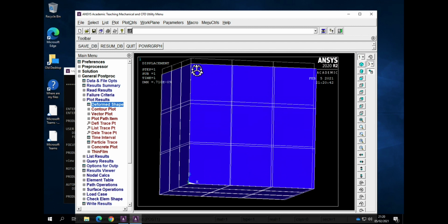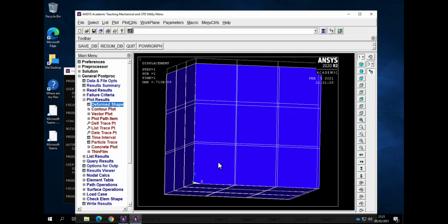I didn't think too much about the direction of the field, the voltage, so I can either extend or contract depending on the electric field orientation. So in this case it's got shorter, and it's also got wider, because it's a bit like a Poisson's ratio. So as it gets thinner in the polarization direction, it'll get fatter in the X and Y directions, normal to the polarization direction.